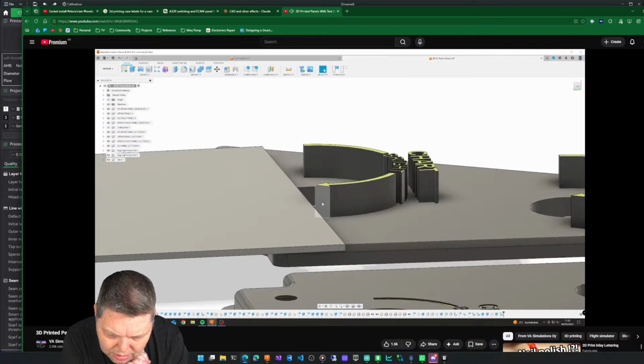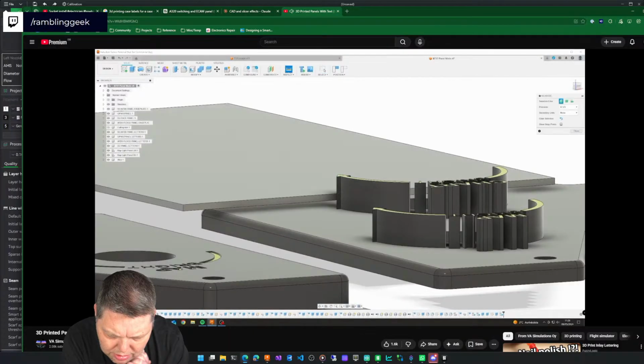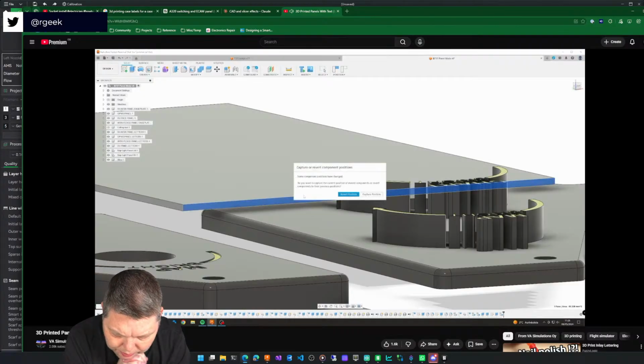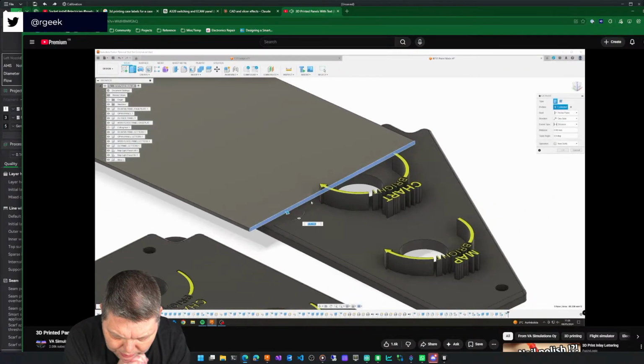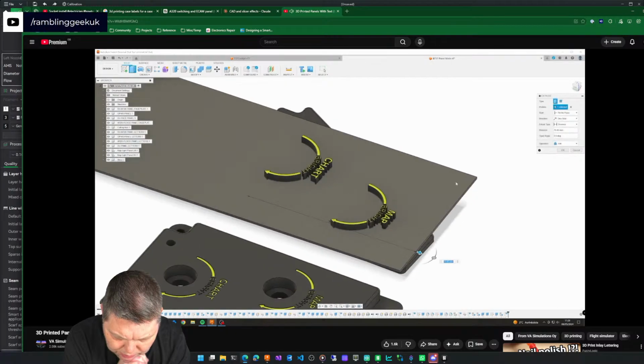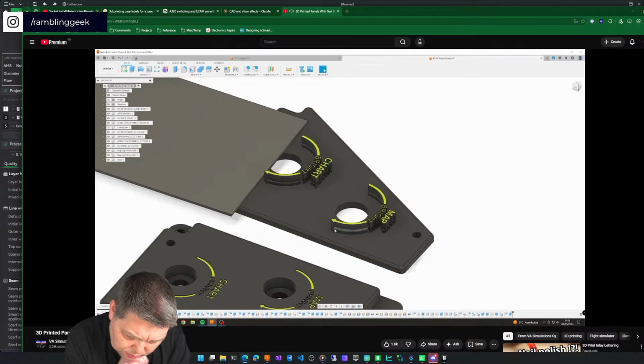And this is why we made this total 5 millimeters. Then we raise this 1 millimeter, and then also this panel is 1 millimeter thick. So now what we do is click this capture position, and we're gonna go ahead and extrude this through the text. And we'll select on the side here, cut, and this is gonna cut all of the text